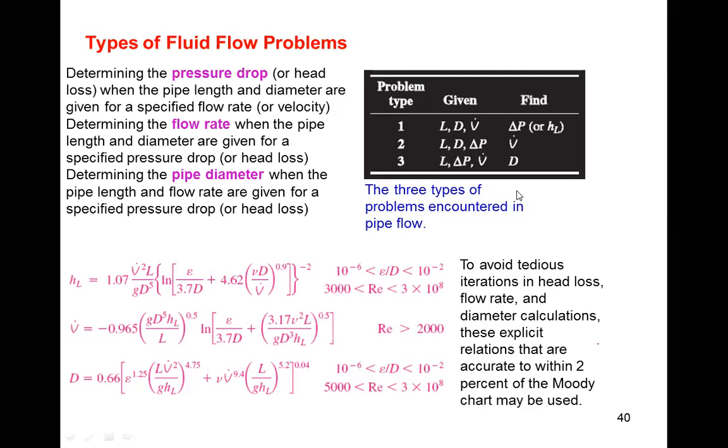No, there are some standard pipeline diameter sizes which are available commercially in the market. If you end up with a fancy diameter by calculation and go to the market, they will say you will not find it. So all your calculation is waste. So you have to always choose a diameter from the available table. There are tables which are commercially available worldwide. So you have to choose those diameters from there.